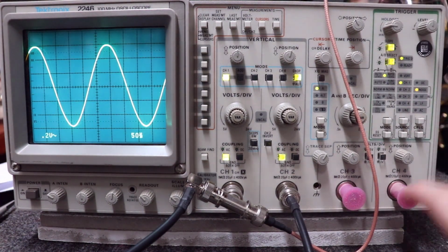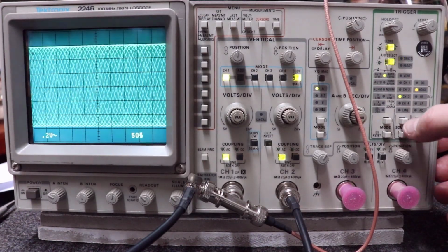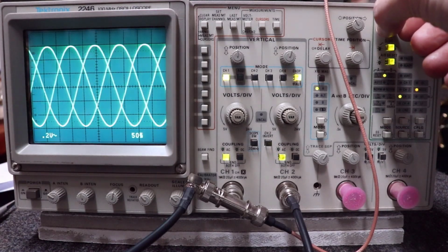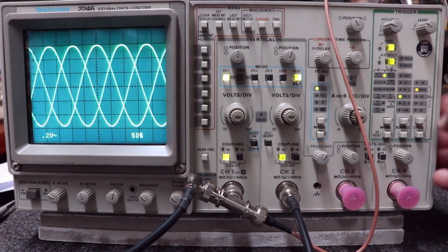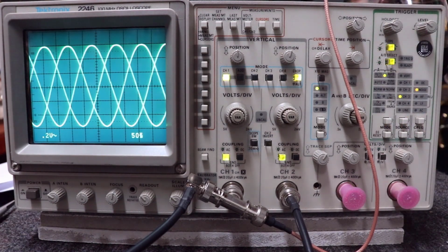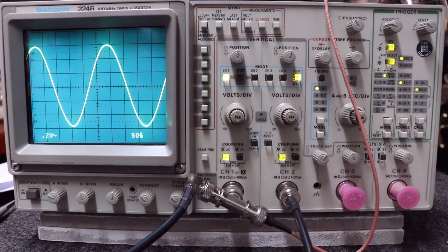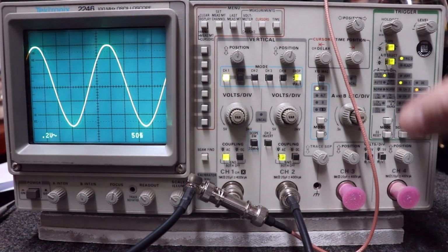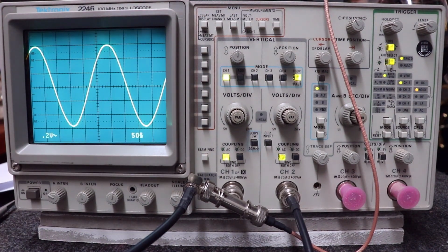You can try everything over here. So let's say your signal's scrolling, you can't get it to lock on, and you're playing over here with different time bases and different levels, and you can't ever get this thing to lock on. There's nothing you can do here that will harm the oscilloscope. Just play around until you get it to lock on. So you don't have to be a scientific expert at this. You can be a little bit of an experimenter and just play around until you get your signal locked on.